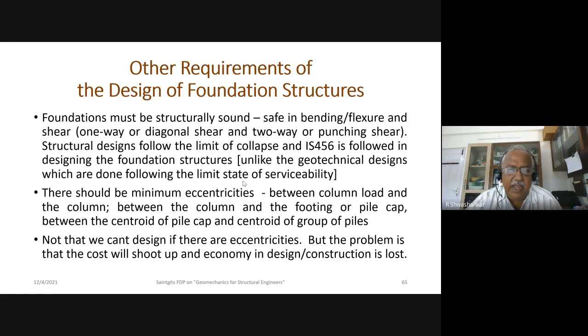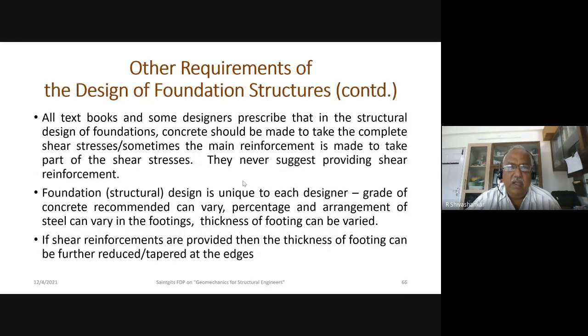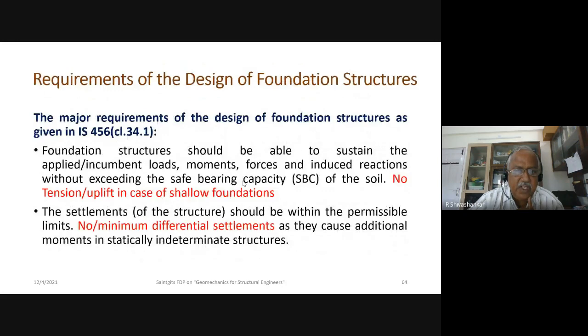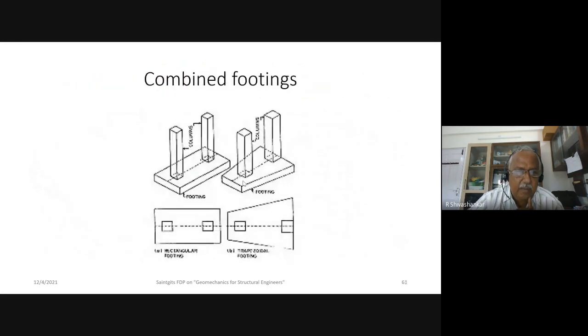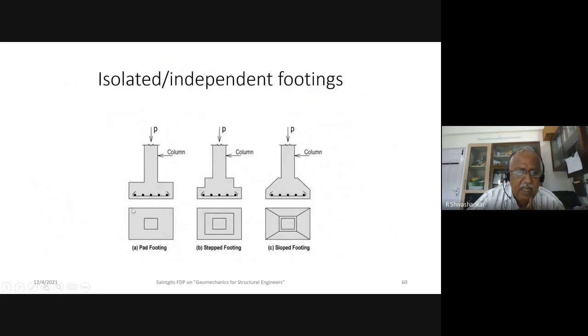We cannot say we cannot design, we have to design, but you have to impress on the client or the owner that the cost of substructure will increase enormously. The foundation cost could be more than the superstructure cost. So as I said, all textbooks teach us that the foundation has to be designed as a slab without shear reinforcement. But you can also have shear reinforcement.